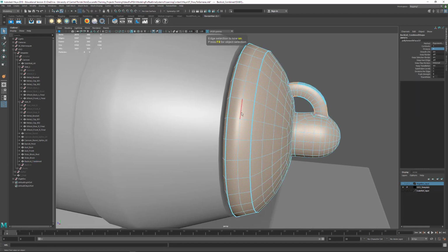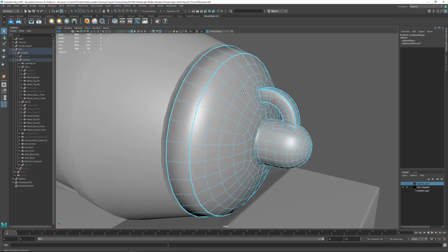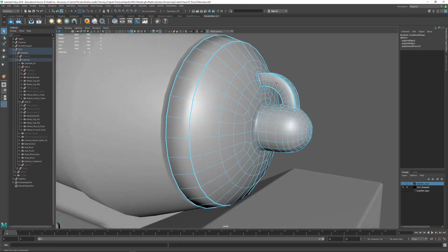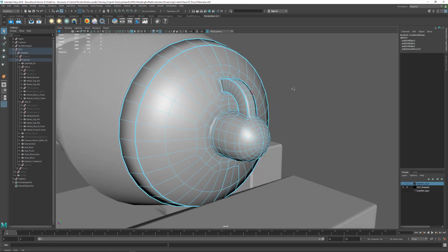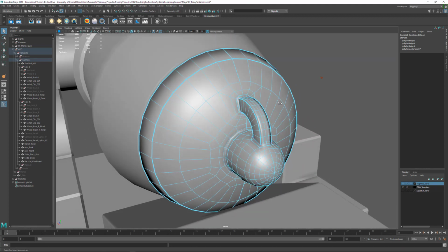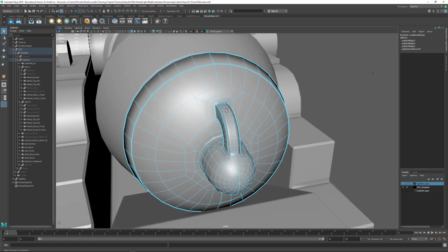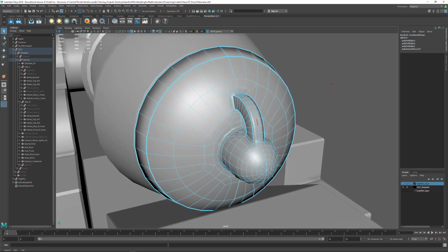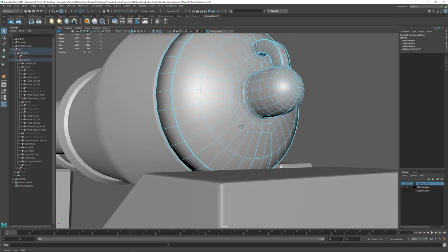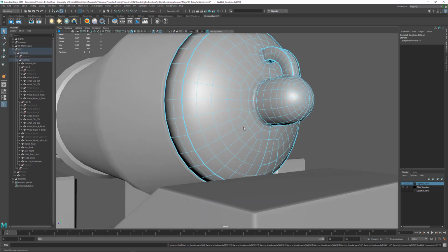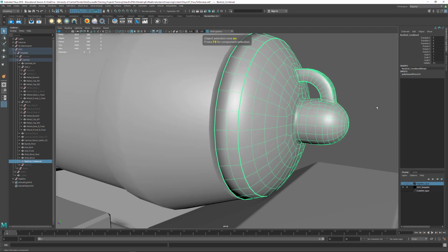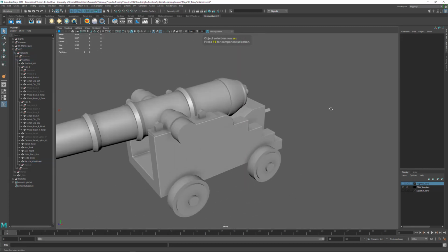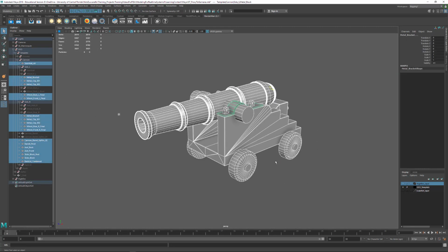So you can see if I double click on this and hit Control backspace, I don't need that part. This is a flat, Control backspace, so I can get rid of some elements like this, Control backspace, and you can see the silhouette didn't change really at all, so I don't exactly need that geometry for those parts. And just going through and doing some removal of that, I'm just going to go back to this point that we got here, and even at this stage maybe we can kind of take a look and see what our